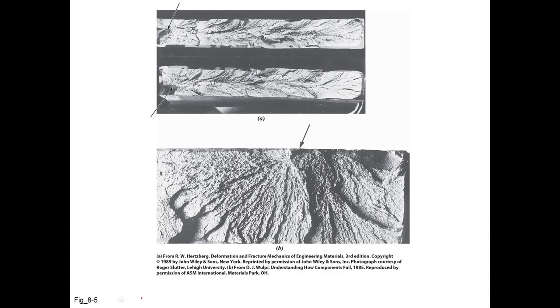For example, that zinc case in the hexagonal close-packed plane, where that was one of the designated slip systems that we saw. The other thing about brittle fractures is that often so-called chevrons mark the point of the crack origin. So a chevron, trying to highlight the chevron there, a chevron there, is a certain type of feature that you can almost think about as a beak opening of a bird, perhaps.